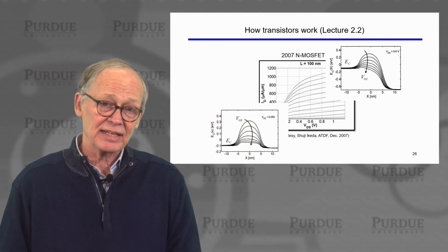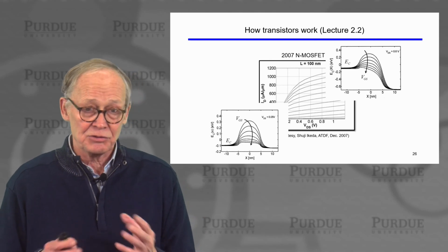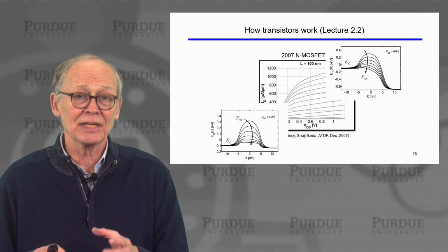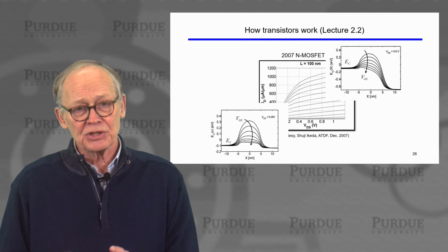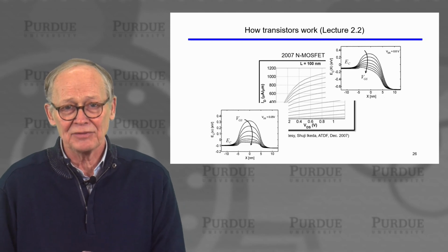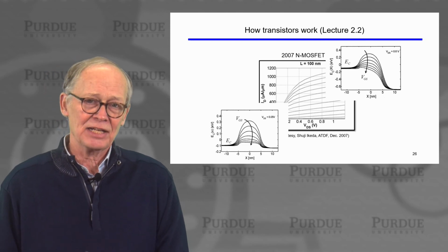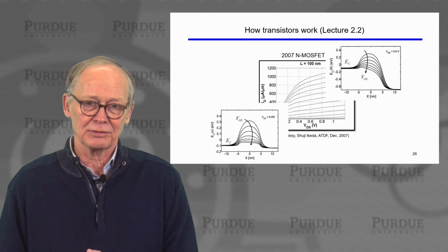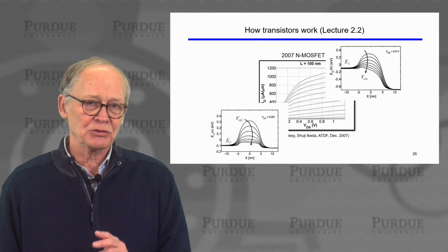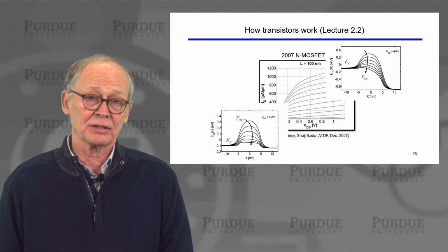That gives the shape of the IV characteristic. The traditional transistor model describes that shape. In very short channel devices, we have ballistic and quasi-ballistic transport. We have to account for that, but it doesn't change the shape of the transistor characteristics. It only changes the magnitude of the current, and with these two simple replacements, we can get the right magnitude of the current.